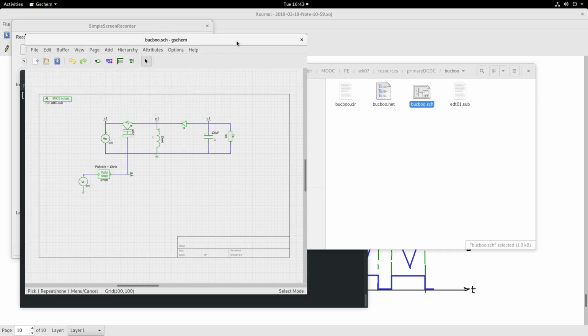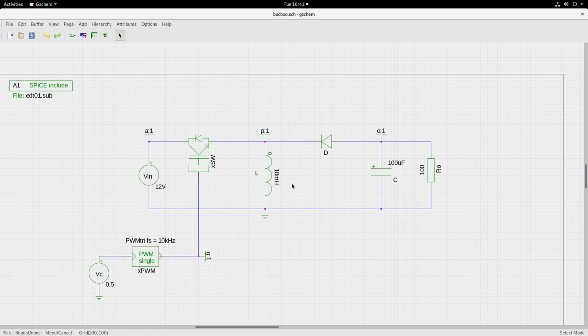So the buck boost converter schematic is like this. You see the throw 1 to pole is this BJT or an IGBT, as you may consider fit, and throw 2 to pole you have this diode D. Look at the placement of the capacitance. Of course, this is the PSpice symbol showing plus here, but you will get a negative voltage. The buck boost will give you a negative voltage, as we had discussed. So let us simulate this. The PWM portion is like I had told for the other two converters. You generate the pulses by giving a voltage here proportional to duty cycle.